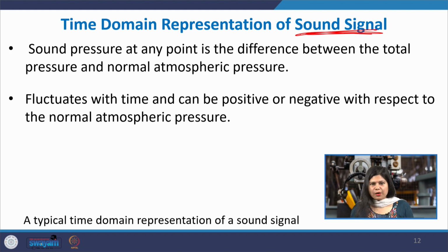So, you measure the sound using a typical instrument like a microphone, where the diaphragm of the microphone vibrates because of the longitudinal sound waves pushing against it. That vibration has some piezoelectric crystals behind it which convert the vibratory motion into a corresponding electrical voltage, which is directly proportional to the amplitude of the vibrations.